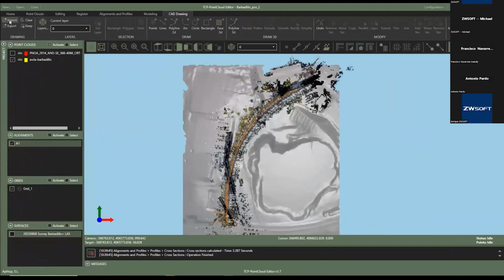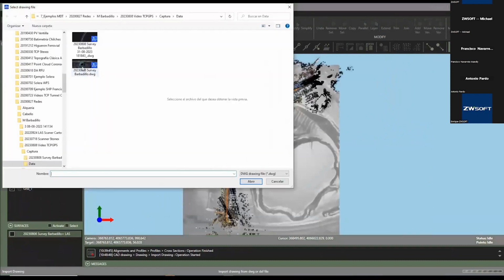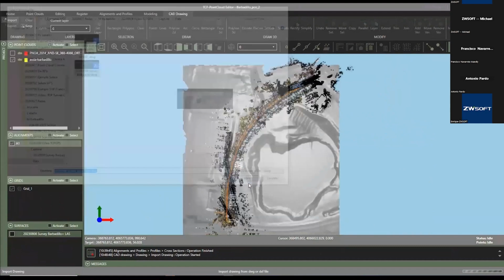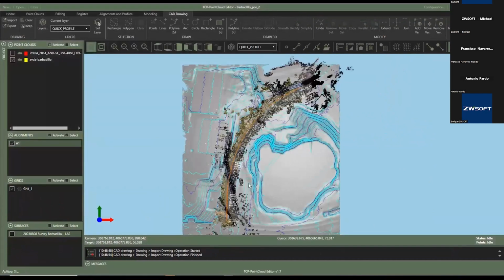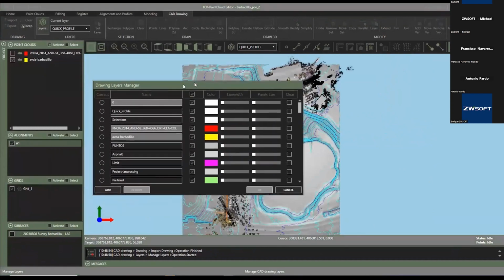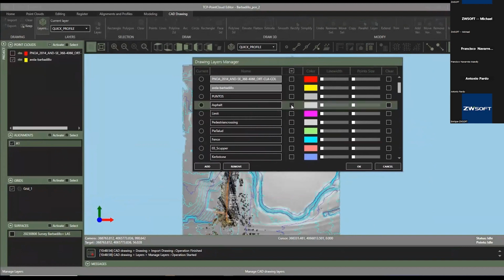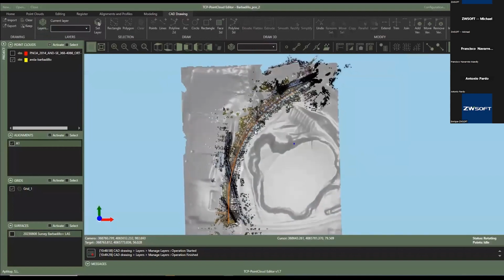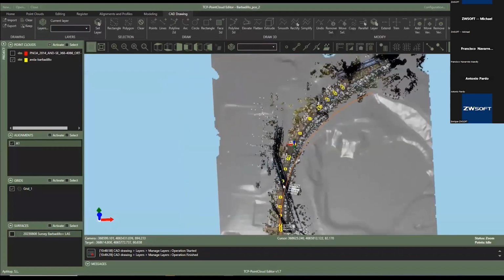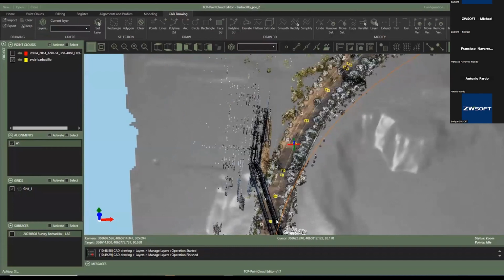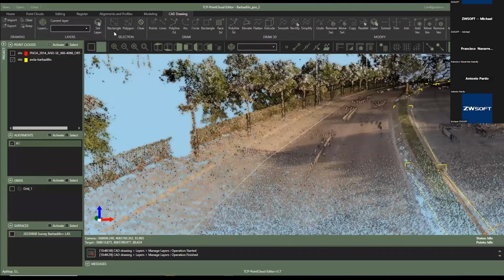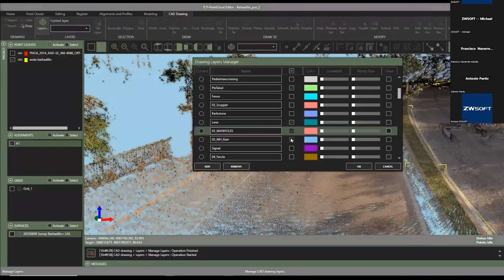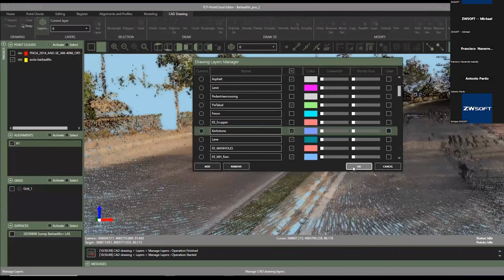And here, we can import the CAD from the ZWCAD that we have. Okay, we can visualize the different break lines and compare them in plan with the point cloud. Here, if we import the CAD drawing, select the layer that we want, and zoom in on the area that we want to focus on. Here is the grid, here is the point cloud, and here is the break line to analyze. Okay, we are going to show more layers, for example, the wheels, the asphalt, etc. And here is all the information.